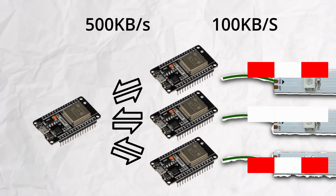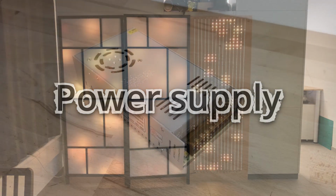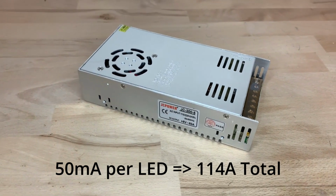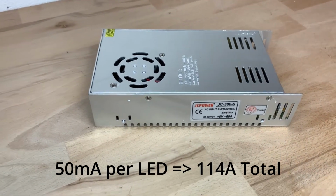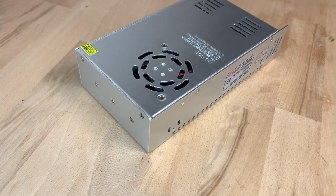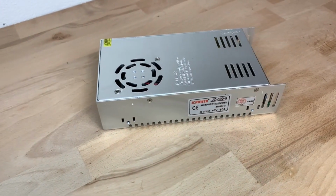Another thing to consider is the power consumption of such an LED wall. Because oh boy, these LEDs are thirsty. Each LED running at full brightness pulls about 50 milliamps. Now multiplying that by the total amount of LEDs on the wall, we get that the whole wall could draw a theoretical current of 120 amps, which is crazy. At these currents you need an industrial looking power supply and also very thick wires. You also have to think about power losses through the strip, as the voltage drop scales with the current running through the wires.